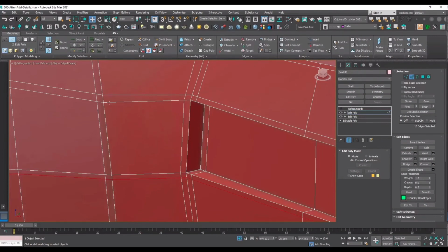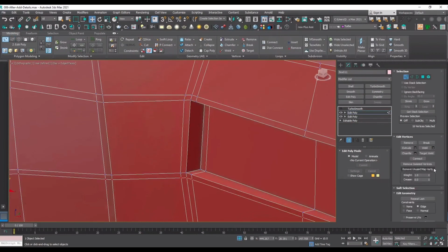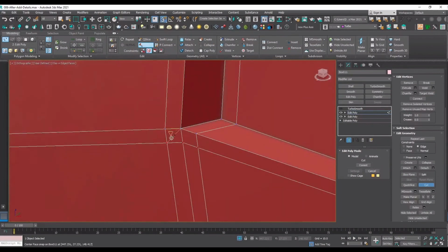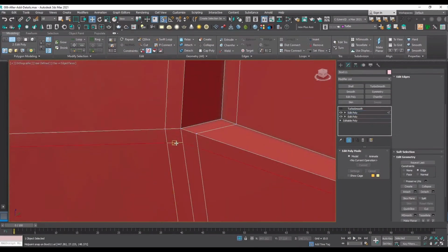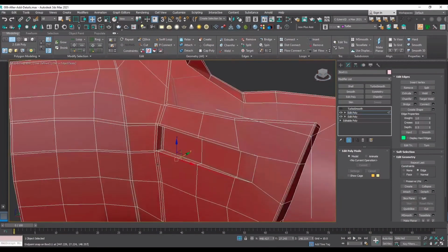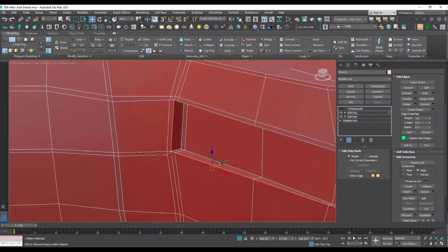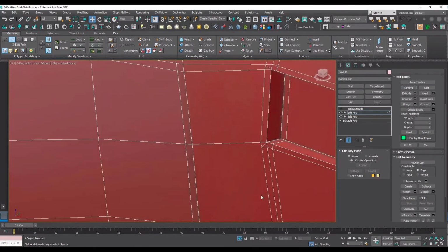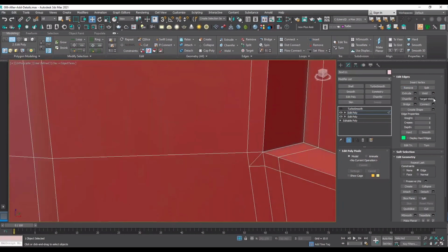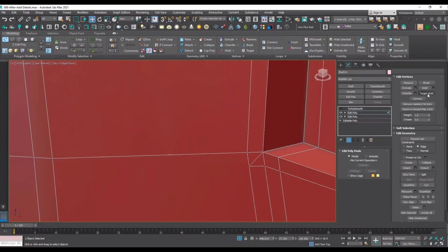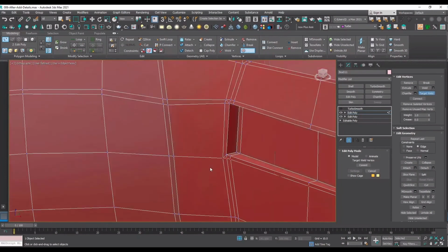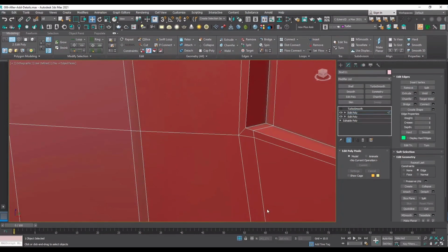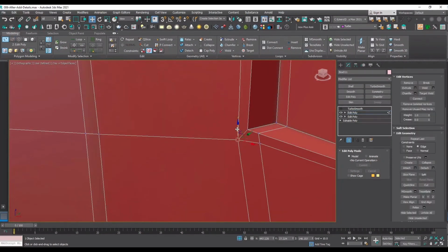And you remember that we will be applying some adjustments here so that we do not get the extra edges all around the mesh with these diagonal lines. And then I'm going to select these edges, Ctrl+Remove, and pick up the Target Weld tool and weld these vertices here, and maybe delete the other edges right there to get a clean topology.